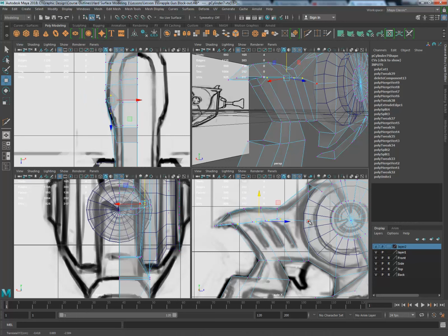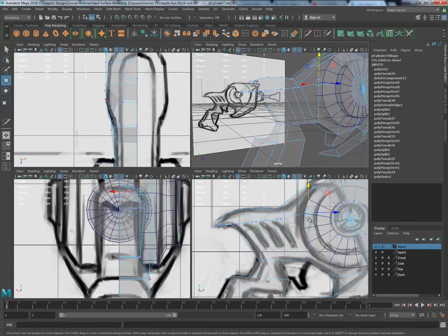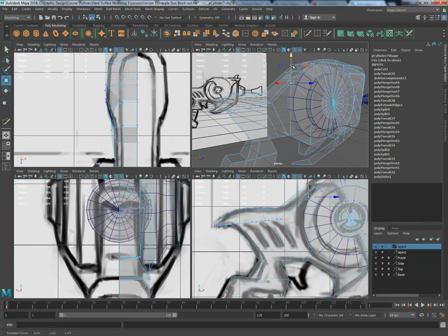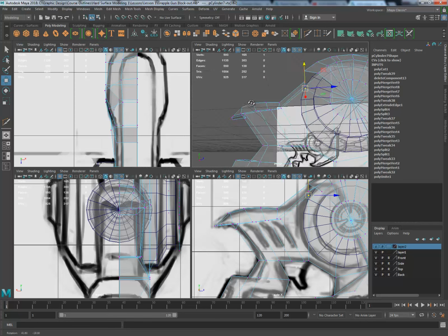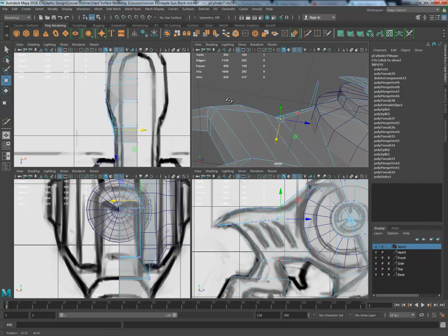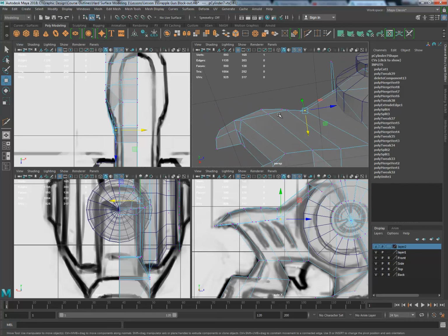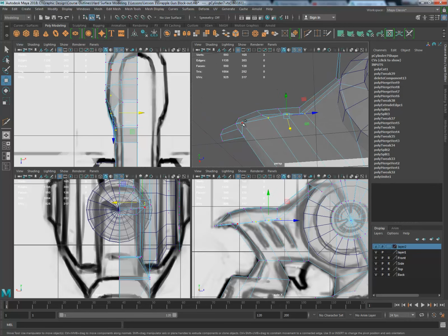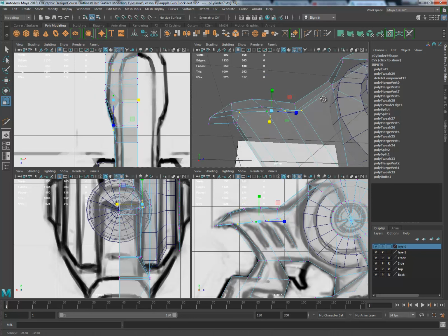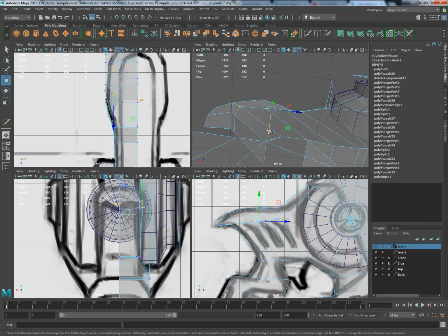It's really important that the geometry all lines up as cleanly as possible so that it's really simple to work with. So you need to make sure you merge verts that don't need to be separate, and use the scale tool to scale lines or edges of vertices, scale them into flat lines wherever necessary.